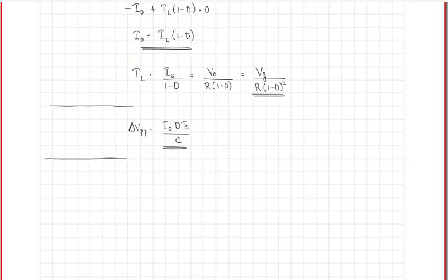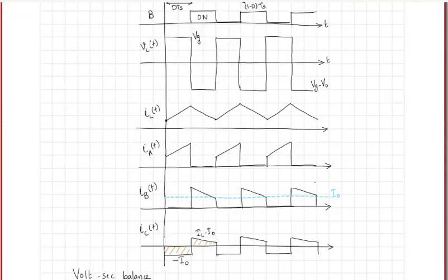So it is again possible that this converter can go into a discontinuous conduction mode if you increase the load resistance, or in other words, if you decrease the average output current, then it is possible that the waveform of the inductor current, which we have shown like this here, can shift, and at some point it would touch 0, right? It would reach here, and on further reducing the load current, this current would become discontinuous, right?